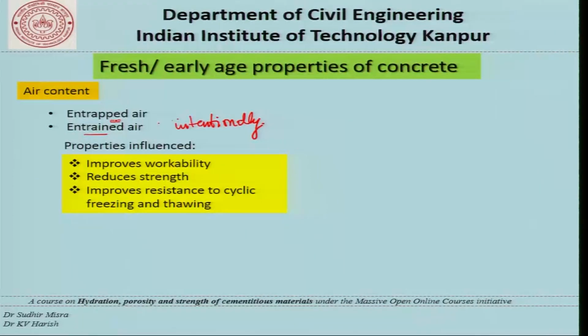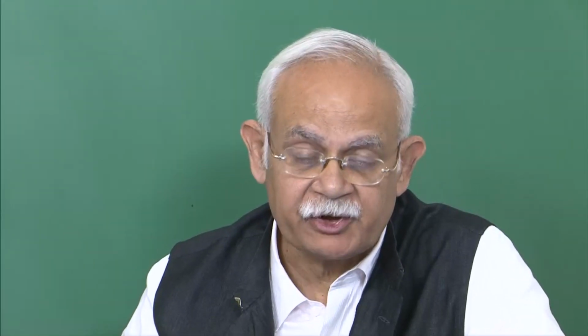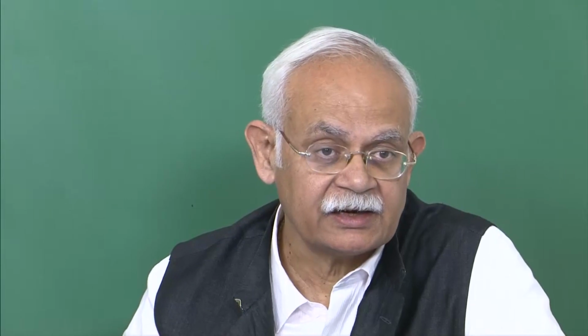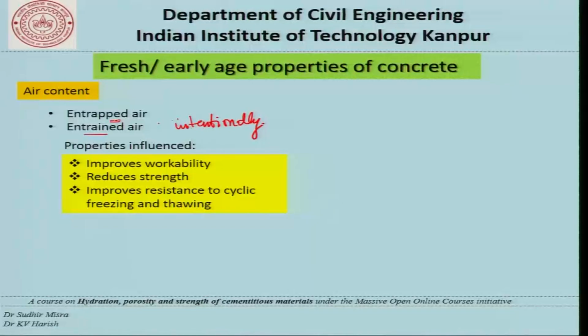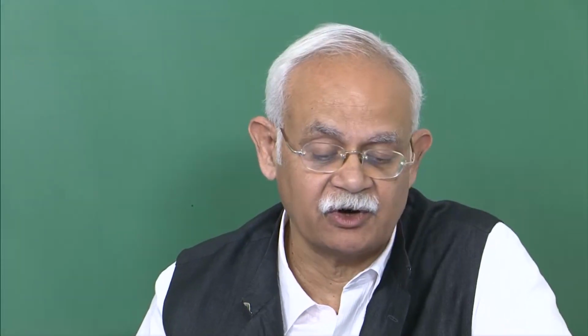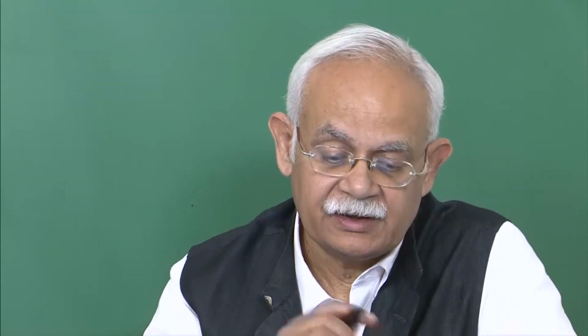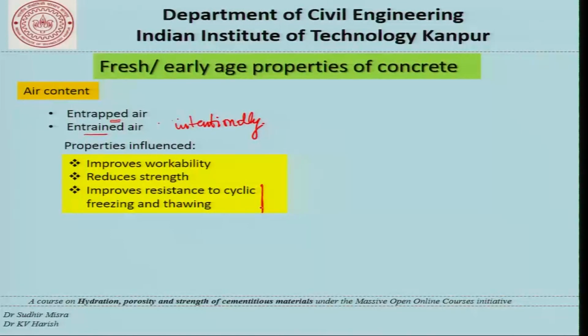However, increased air content also has the danger of contributing to reduced strength because at the end of it, air content is basically voids, and we do not want the air content to reach levels where those voids become a source of introducing a problem as far as strength of the concrete is concerned. Air content is prescribed in concretes which are used in environments with cyclic freezing and thawing.